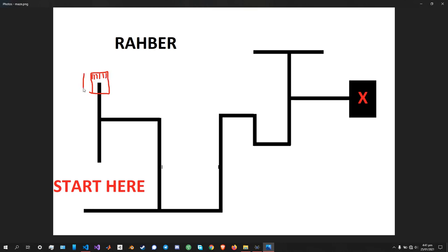So what we're going to do is turn this left motor down and this one up, and it's going to turn like this. When it is about to reach this left sensor, this one is going to click here first. If this sensor goes like this and then crosses this line, the left sensor crosses this line, we can be rest assured that these two sensors are now above the middle line here, right?